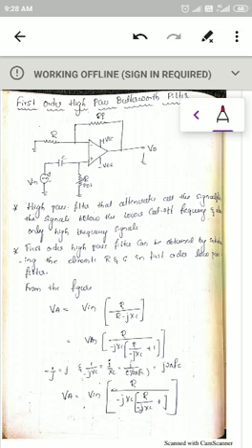Okay, so this is also realized using an RC network. This is a schematic view of your high pass filter. Here the filter is a high pass filter, which passes only higher frequency signals and blocks the low frequency signals. It attenuates all the signals below the lower cutoff frequency. The first order high pass filter can be obtained once again using the RC elements. So this is the equivalent circuit of this one.